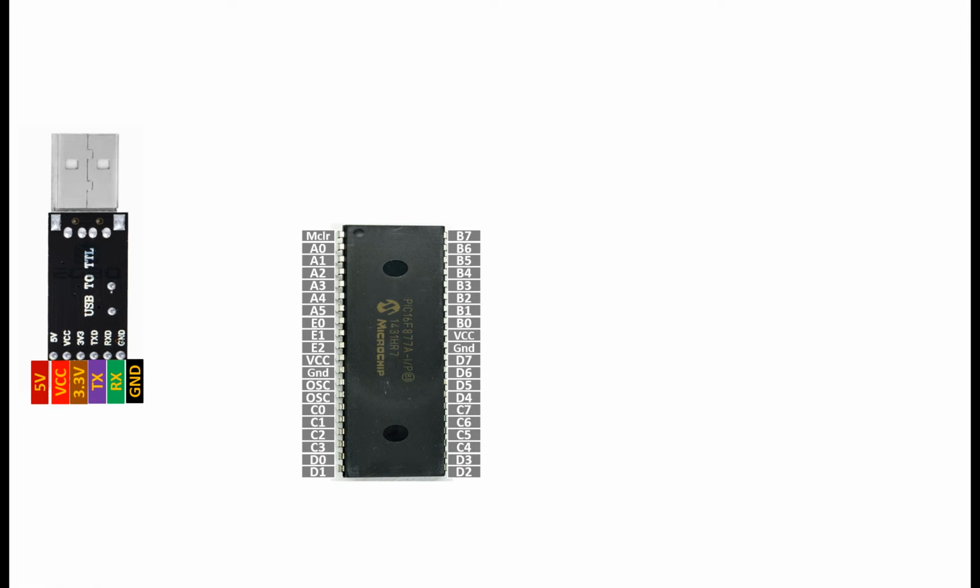Now these are the UART protocol pins TX and RX, and the PIC's UART protocol is at pins C6 and C7. But we are going to use a software serial library, so we are not going to use these 2 pins at all. We will use some other pins. We will transfer the UART function to some other pins using the software. So I'm going to use D0 and D1, D0 as the RX pin and D1 as the TX pin. So this will be our software UART port.